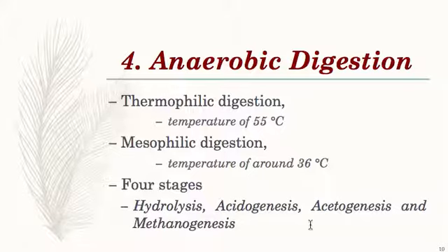Acetogenesis is the second stage in the four stages of the anaerobic digestion, a biological reaction where volatile fatty acids are converted into acetic acid, carbon dioxide, and hydrogen molecules. This is the procedure to carry out all of this methodology for the treatment in the anaerobic digestion process. Acetogenesis is a process through which acetate is produced either by the reduction of carbon dioxide or by the reduction of organic acids. The different bacterial species that are capable of acetogenesis are collectively termed acetogens.